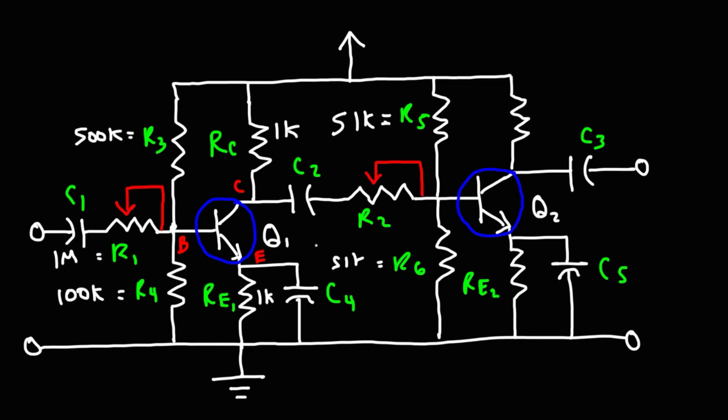But now the voltage at the second stage will be higher. So I want VB to be higher. That is the potential at the base. Because if VB is too low, then a high input voltage could drive it to cutoff or saturation.